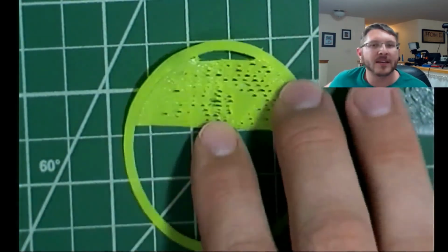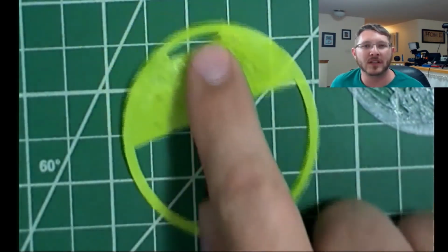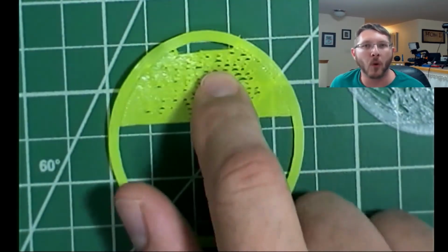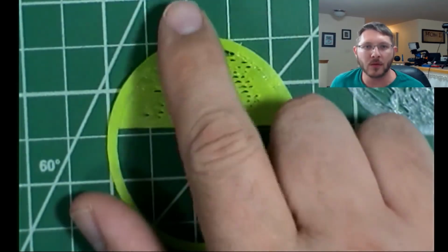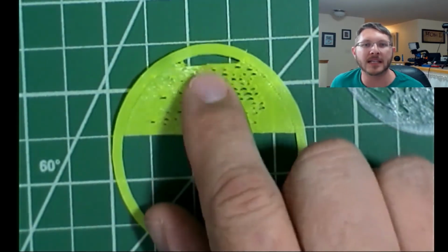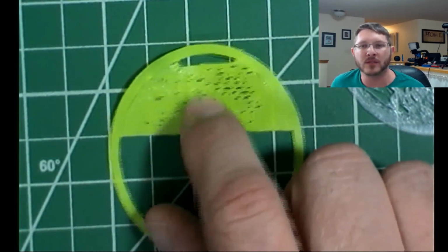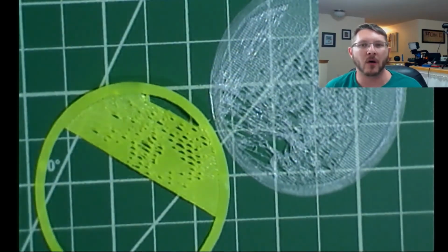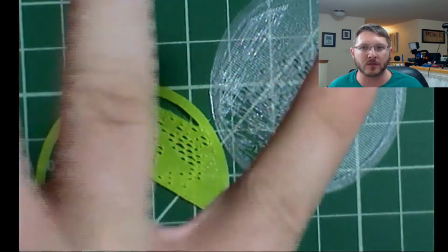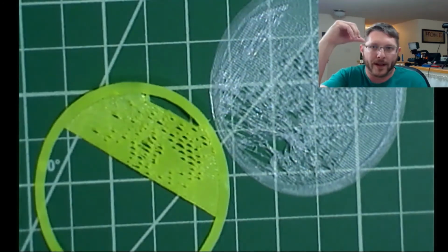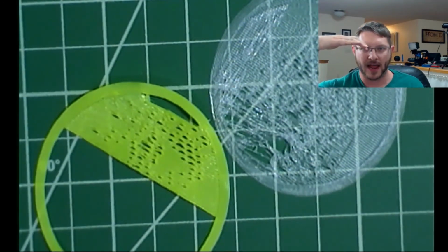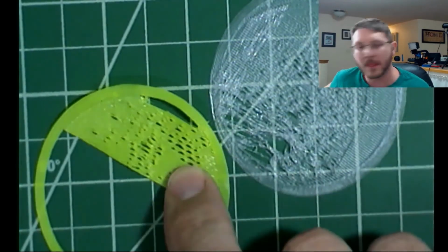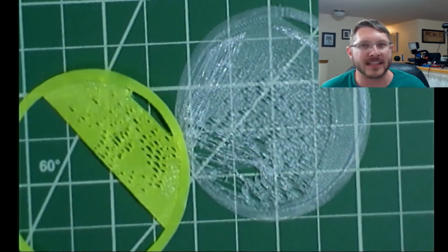So the only thing I could think of was this is what it looks like, okay, because that is what it was when you have poor bed adhesion. It was good on the sides, but as it made the rest of it, what was happening was this was pulling loose. The plastic was pulling loose from the bed, and so it was basically warping up. It was trying to lay it flat, but it was warping up like that because it wasn't sticking well. So each one of those lines that it drew wasn't sticking down to the bed.